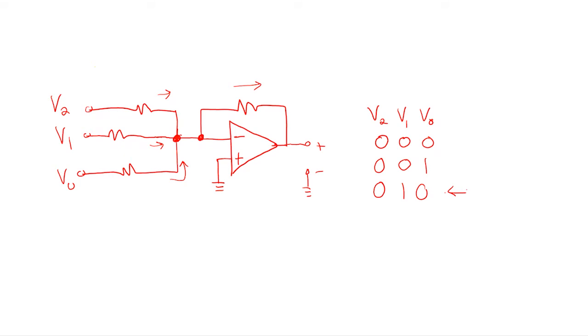So this is a DAC. As you walk through my table, this guy will be the smallest number, and then an equal amount bigger each time, until it gets up to 3 volts, I think, at the high end. That's the basic way that people make what we call a DAC.